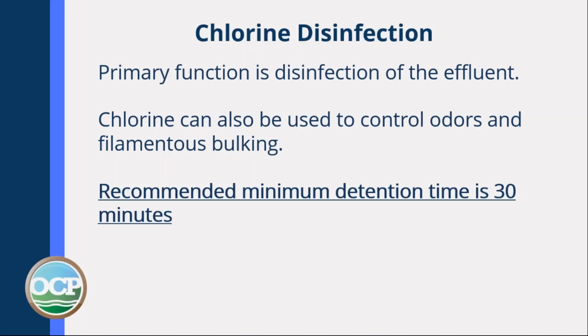You don't want to put pathogens out into the receiving streams. Chlorine can also be used to control odors and control filamentous bulking. The recommended minimum detention time is 30 minutes for the water once chlorine is added.